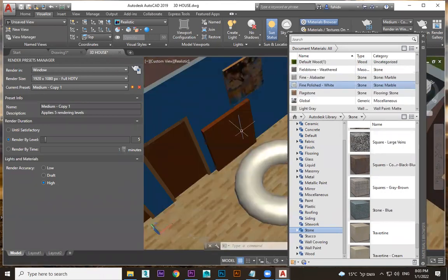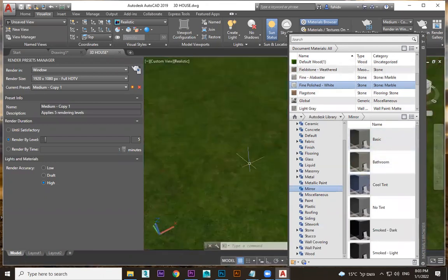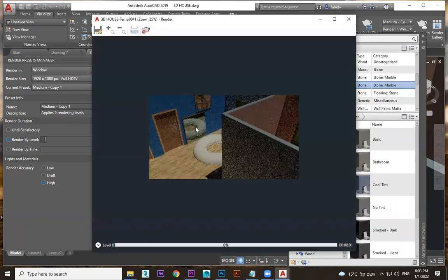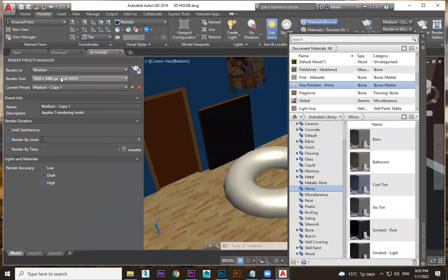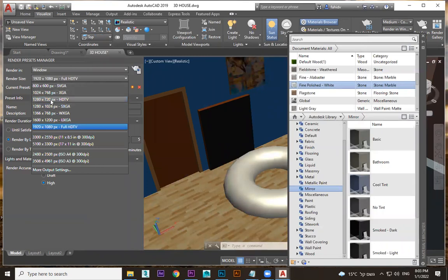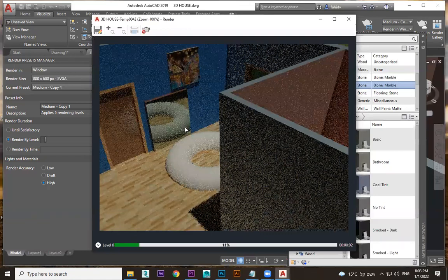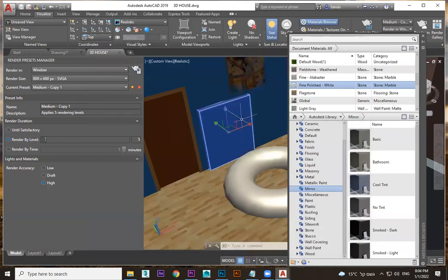Then for the control, select here, this one I want to make a mirror. Click on the mirror, do the basic mirror. The different types of mirror are there, and the quality will be different. There is a light, that's the reason I will be able to see it properly. Through this one, the reflection is visible because it's a mirror now. The quality I had set to high, I don't need that for the time being, so let it be smaller, so I get a result quickly, okay? Mirror material you need to check with the light. Without light, if you check, you don't get a good result. I won't wait till 100%, okay?